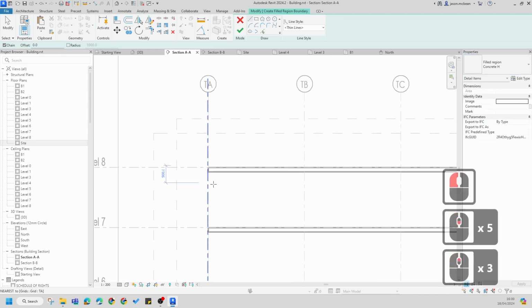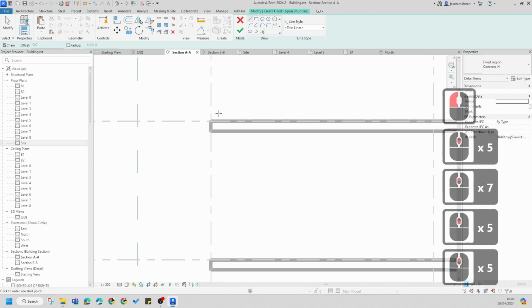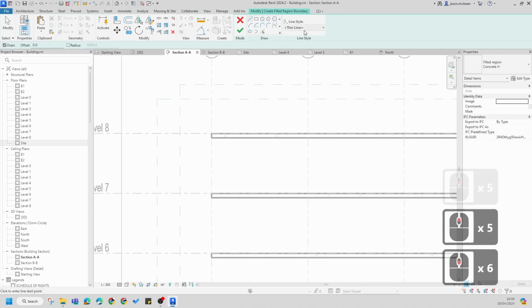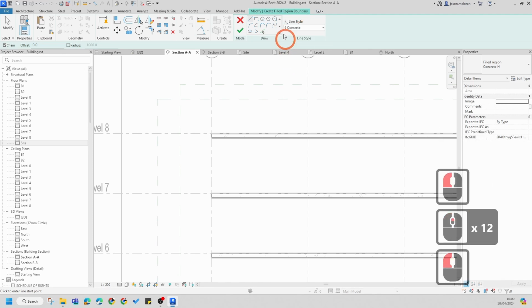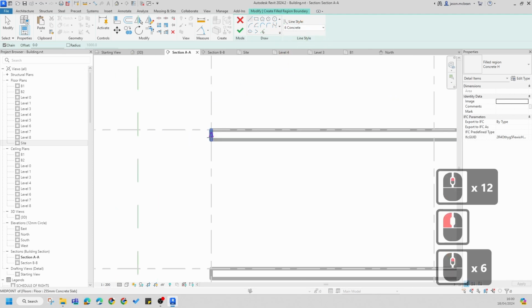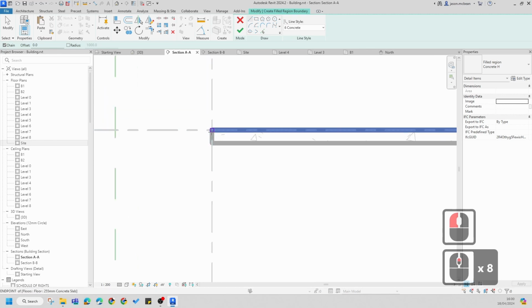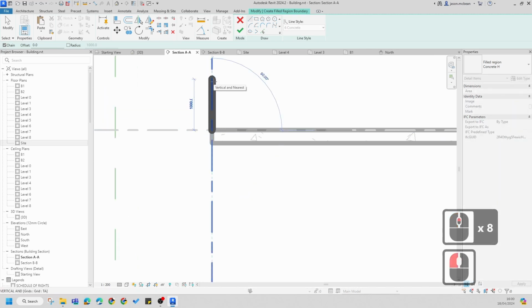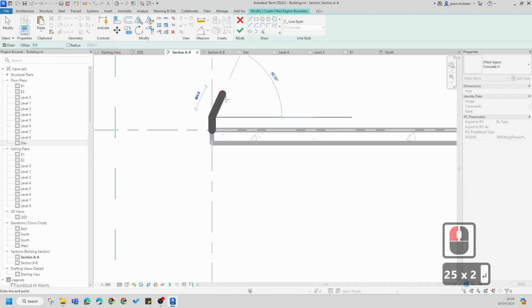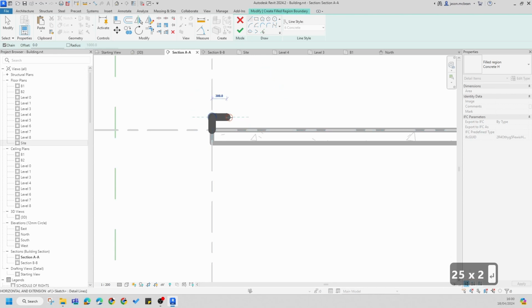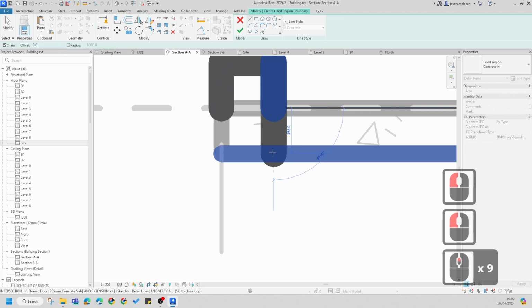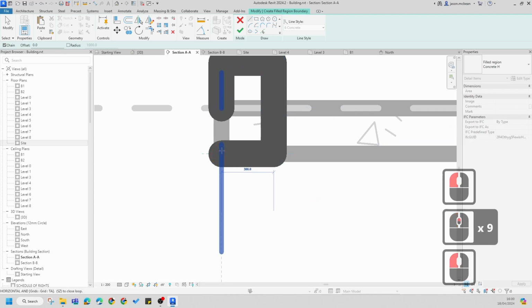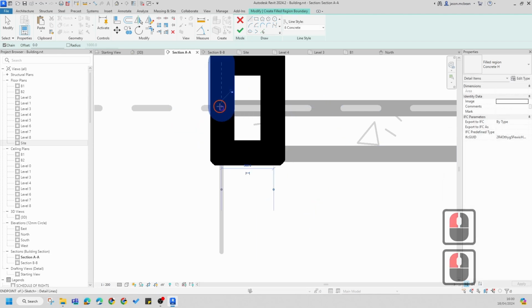Now, I'm going to start drafting over this edge here. I'm going to create an upstand beam and a downstand beam. Make sure that you match the line work with whatever you're drafting over. So 6 with concrete or structure. If I start drafting an upstand beam here, let's make this 255 for now. Remember, this is going to change, make that 300, come back down. Now I'm going to draw through this object, come back through here, and close that there.